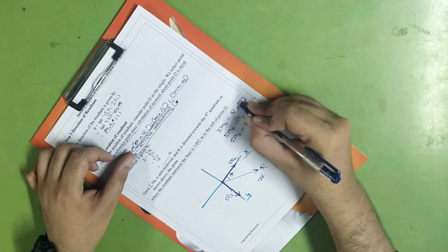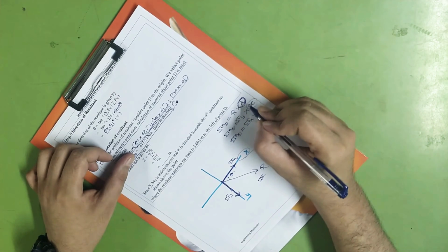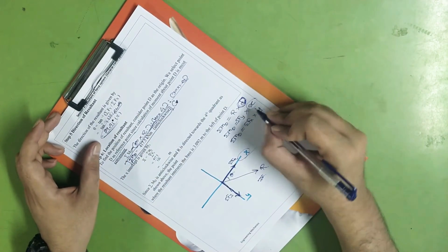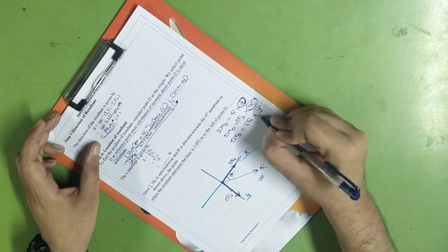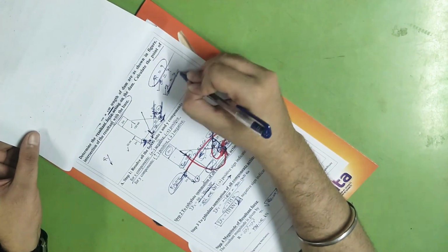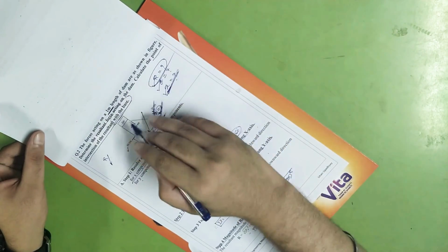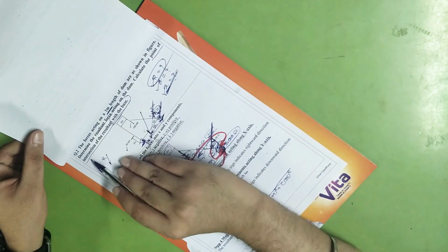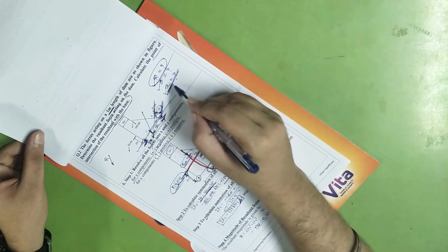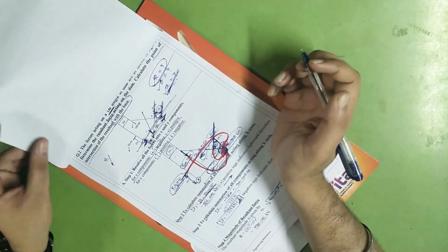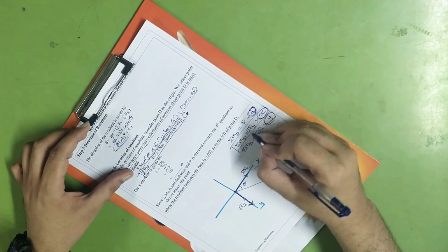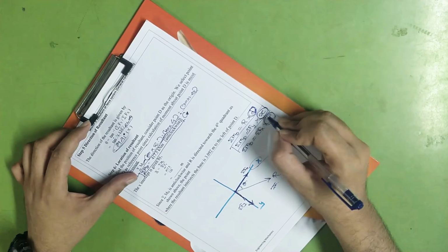Remember, here I am getting the perpendicular distance of that inclined resultant, because the resultant is inclined at 79.19 degrees. Here I will get the X intercept and here the Y intercept. Looking at the question, what they are asking is the point of intersection of the resultant with the base. Since the base is horizontal, we are calculating the X intercept. Applying this formula, summation of MD is equal to summation of Fy into x.